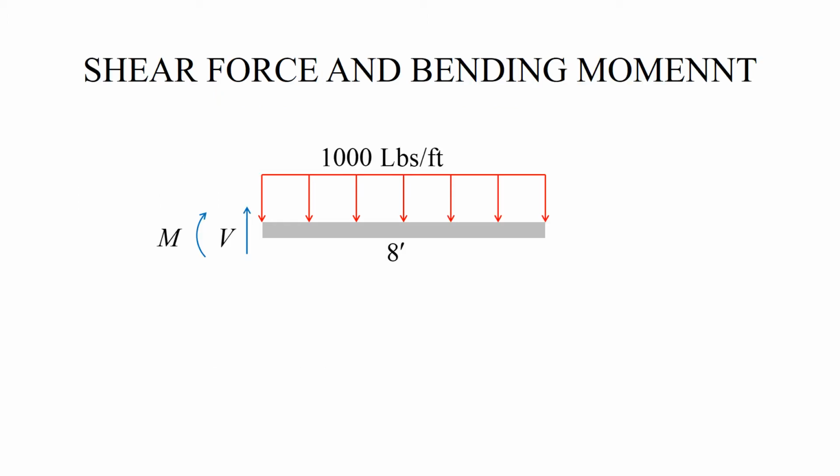For a uniformly loaded cantilever beam, there is no need to construct shear force and bending moment diagrams. It is clear that the maximum bending and shear will be at the wall, and accordingly it is sufficient to draw a free body diagram showing M and V. Let me point out that I show M and V as dictated by the sign convention for internal forces. This is helpful because the signs will clearly indicate what should be done when I conduct stress analysis.